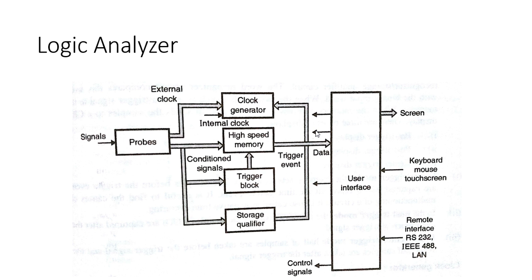So it is preferred for troubleshooting of problems related to computer hardware, and generally this method is called the asynchronous method. Now if you talk about the logic state analyzer, this was the logic timing analyzer. In a logic state analyzer, the data is sampled when the clock signals are synchronized with the measured device. The data sample is again stored in memory, and this stored information is displayed in the form of a binary or hexadecimal format. Whenever you want to do software troubleshooting, such logic state analyzers are used.